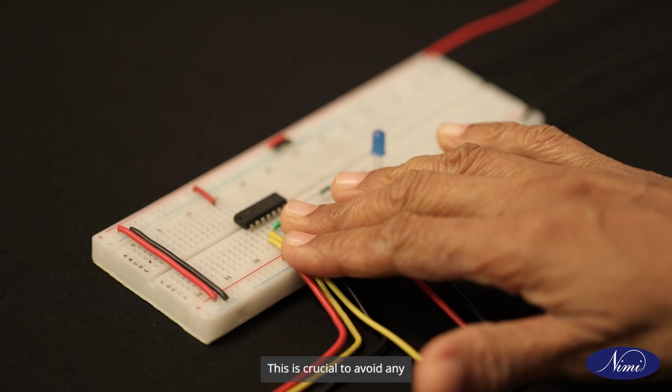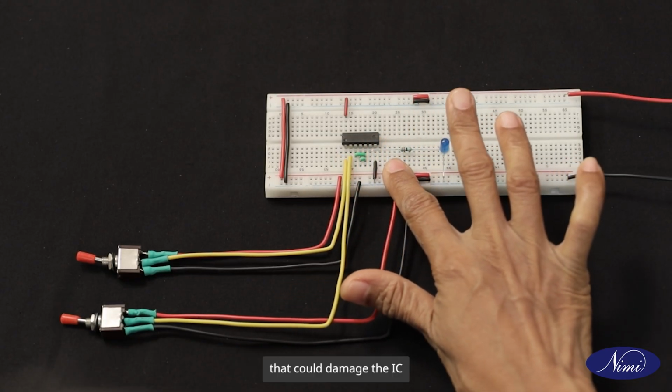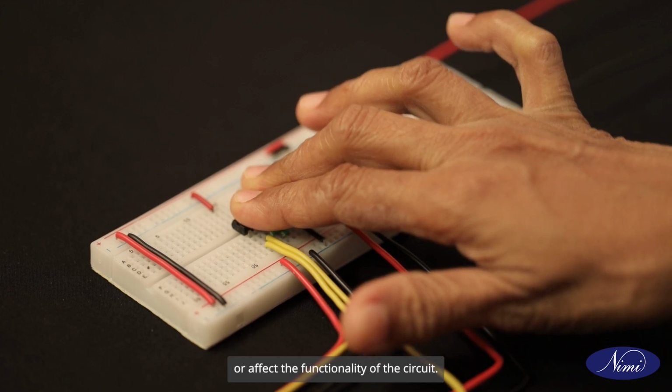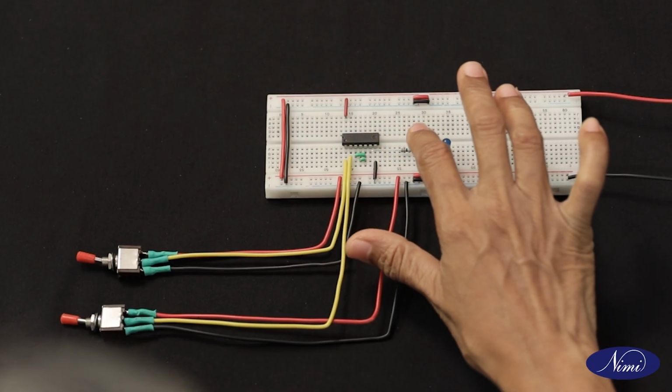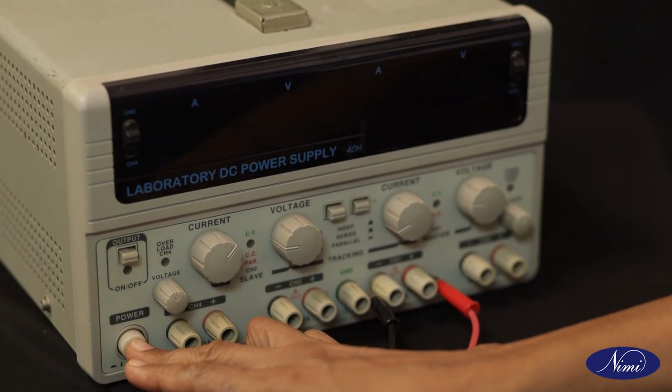Before you power up, get your assembled gate circuit checked. This is crucial to avoid any short circuits or incorrect connections that could damage the IC or affect the functionality of the circuit. With everything checked, switch on the 5 volt DC supply.